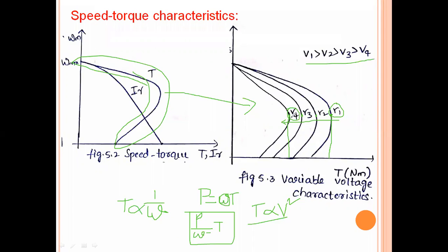But during the maximum torque point, both are showing linear relationships as discussed here. That means this type of characteristic is very much suitable where the torque reduces with the speed demand, which means the speed and torque both are reducing. In those applications also, induction motor is very much suitable.